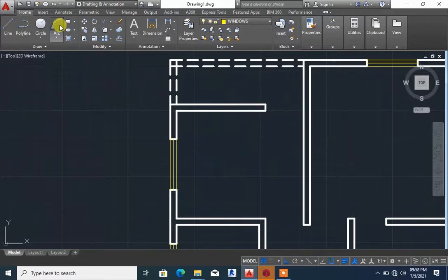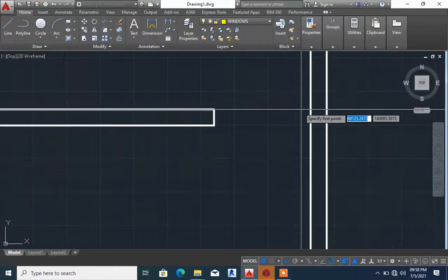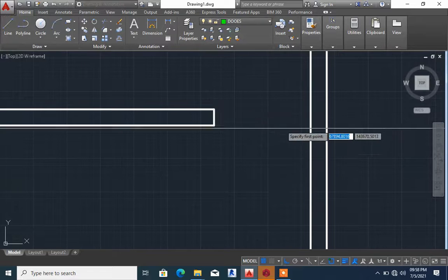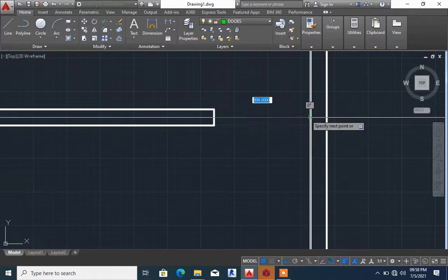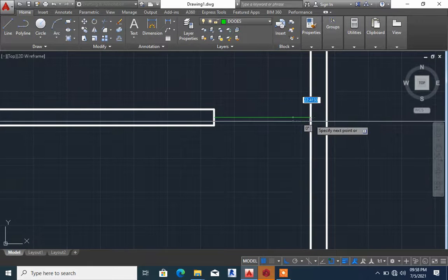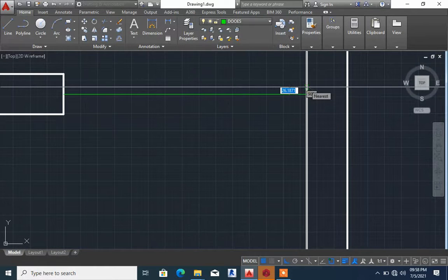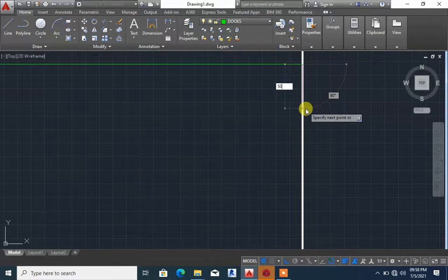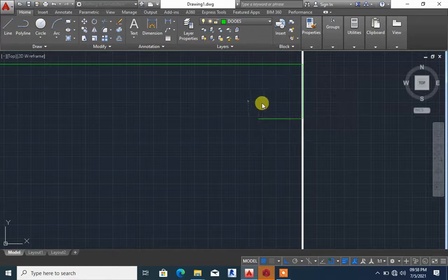You can go to arc. First of all, pick line. Now let's take the door layer, line. Come to the center. You can choose to come down a little bit, type 50, then 50 here, and there.